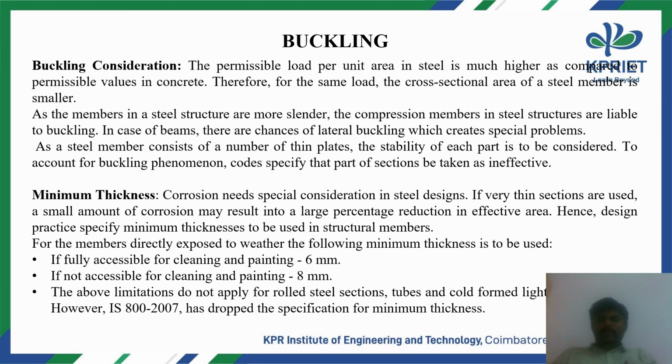The compression members in steel structures are liable to buckling. In case of beams, there are chances of lateral buckling. Lateral means a horizontal load, which creates special problems. As a steel member consists of a number of thin plates, the stability of each part is to be considered. To account for the buckling phenomena, codes specify that parts of sections be taken as ineffective.